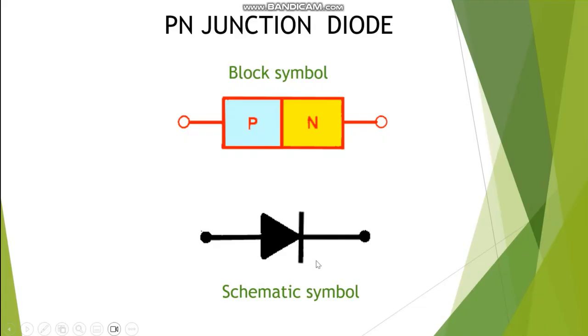If you were to remove that vertical line and flip it to the side, it would look like a negative. So that's the cathode side, typically denoted with a K. This is the anode side. So we usually identify the cathode side on your diode, it's going to have a stripe. That would be the cathode side.